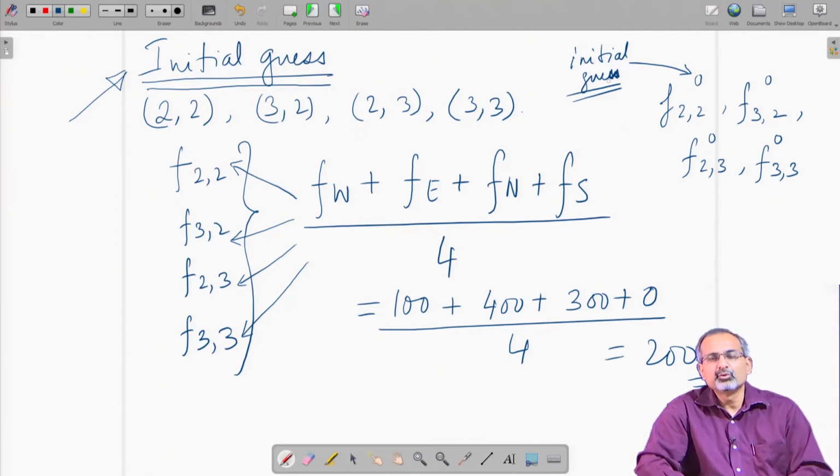However, if you are putting a Neumann boundary condition somewhere in the domain, then even the boundary condition at that particular boundary where the Neumann boundary condition has been imposed will evolve iteratively. Like it is going to evolve in the inner grid points, the values will also get evolved at a boundary where you have imposed a Neumann boundary condition. So, there is a difference between how boundary condition values have to be updated in a Neumann case.